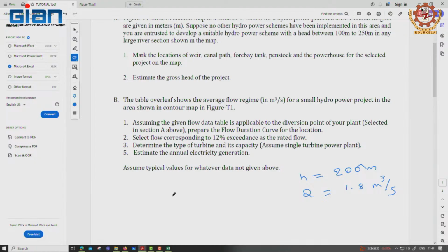And then our equation is efficiency into Q rho G H, efficiency we have to get, right. So, the efficiency will be efficiency of the turbine, efficiency of the generator, efficiency of the transformer. Let us stop there, otherwise you can put the transmission line, etc.